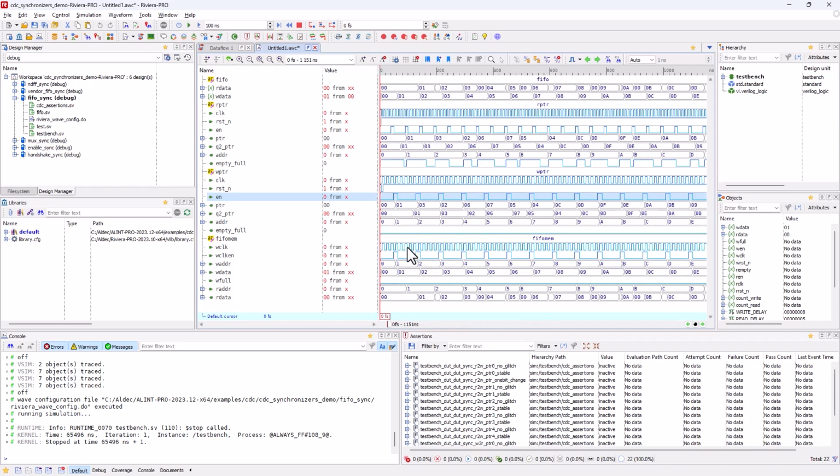So, now that we've looked at those assertions, we can very quickly go to the beginning of the simulation waveform, just to take a look at how the FIFO synchronizer behaves. So, to start off, each of these lines here for the two enable signals dictate when each of the FIFO blocks are told that they can either read or write to or from the memory. Specifically, I have it set so that each of the enables goes off one right after the next, just in this pattern. So it's not like multiple consecutive reads or multiple consecutive writes, just one after another.